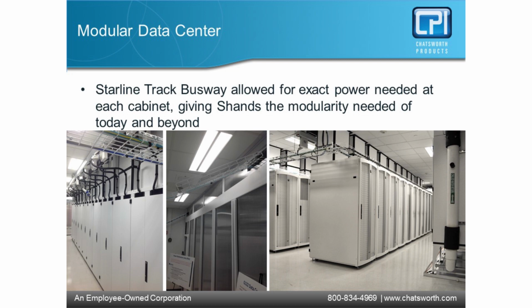And the recommendation that we always give is, firstly, there's an element of criticality with the gear that you're working on. Is this a critical load? And if so, then you can make connectivity to that live from a power perspective. But you also need to understand your arc flash potential there. So, as part of the scenarios, we always recommend to the end user that they understand the incident energy depending upon their power architecture that they've deployed in the facility, and that their workforce wear the appropriate PPE based upon whatever that arc flash calculation comes back to.